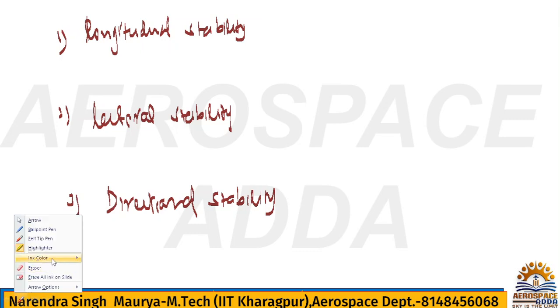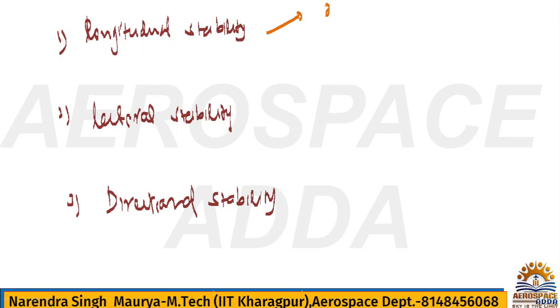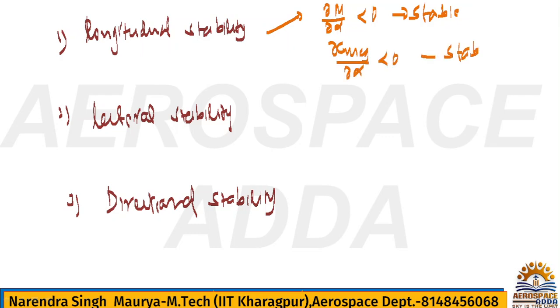Now if you check, ∂M/∂α less than 0 is stable. For the stable criterion I'm writing this. Also you can write ∂Cm about CG. So ∂Cm,cg/∂α less than 0, this was stable, as you said. For stable only I'm writing.